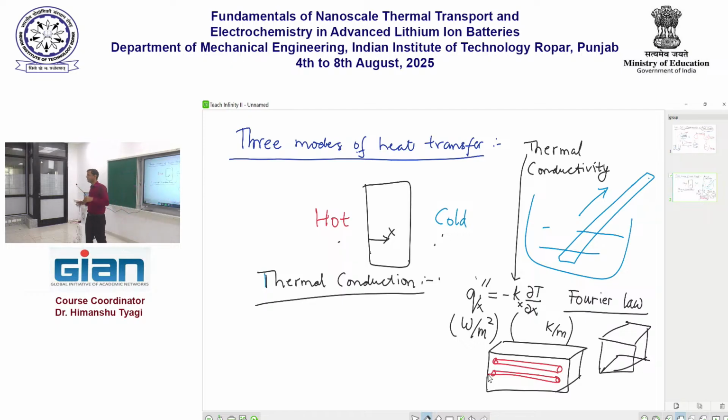of some other plastic or polymer, and in this case, you can clearly expect that heat transfer in the three directions will be different from each other. Along the direction of the carbon fiber, heat will be able to flow very easily, whereas in the other two directions it may not be able to flow that easily.